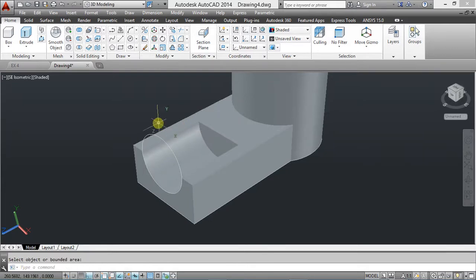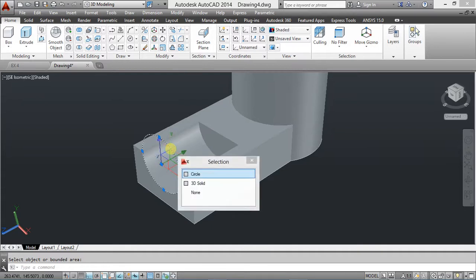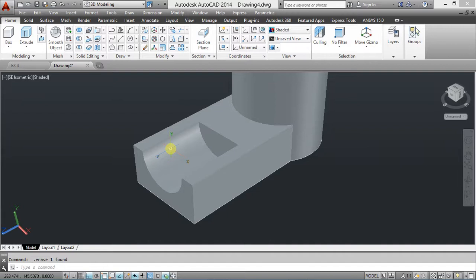I remove it inside. If you press pull inside a solid, you will remove the portion, but if you press pull it outside from the original sketch solid, you will add a surface. That is the difference between press pull in different directions.